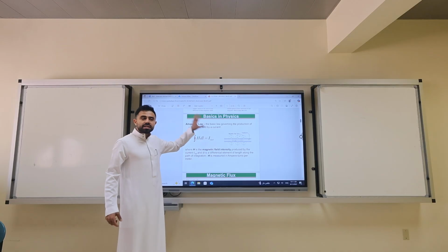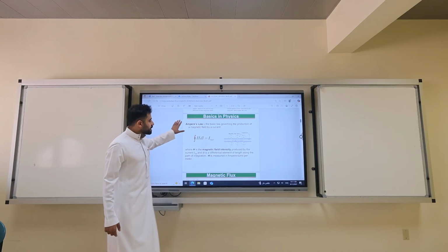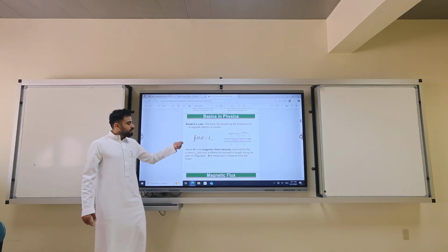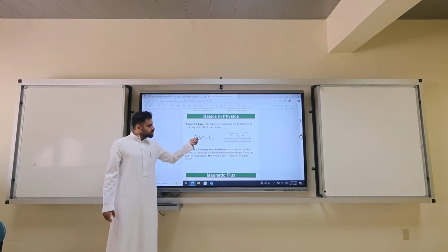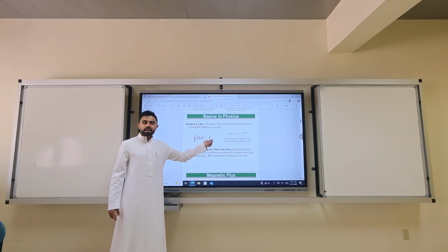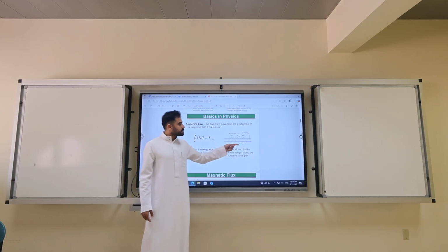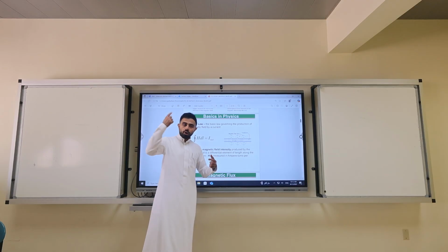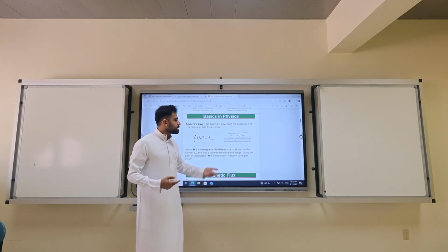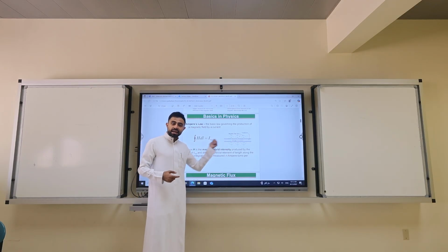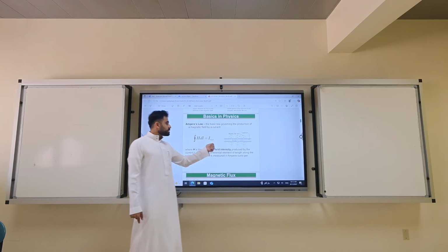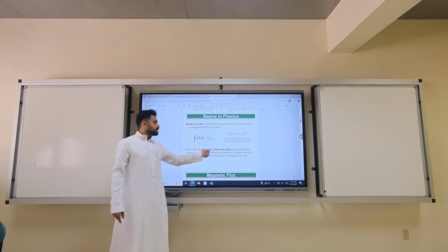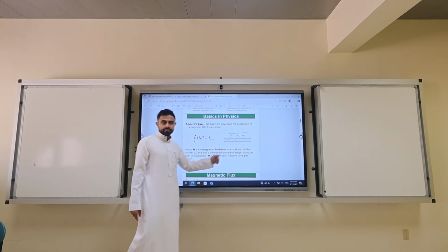This slide does not explain Ampere's law in detail, but it gives you an indication that to get the H, you also need to increase the net current. What's the net current? It's the current that moves through the conductor. If you push more current, or if you increase coils, you increase the net current. If you increase the net current along the path, you increase the magnetic field intensity.